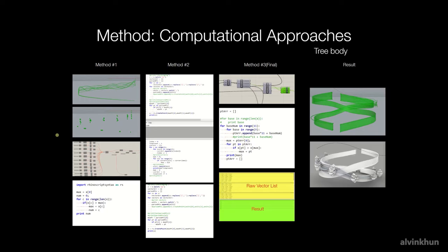The final method is optimized and easy to configure. Firstly, we deconstruct the curve and only feed the z vector into GH, and then change the data access of the GH into list access, so that it will automatically pass the data into native array type. We then divide the length of the array by the total number of branches in order to get the list containing every nth point in each branch. Therefore, we can easily compare and obtain the highest and lowest points from a set of curves.